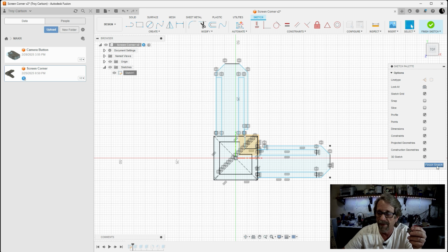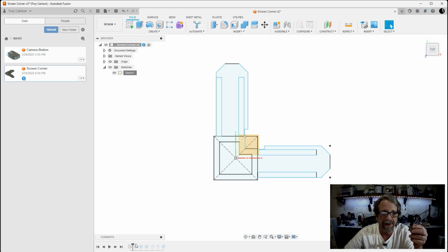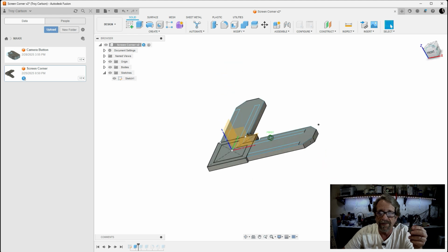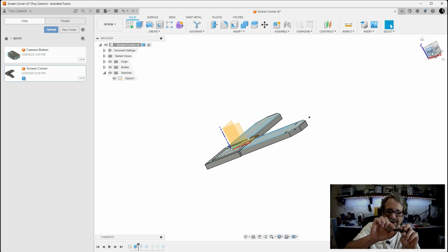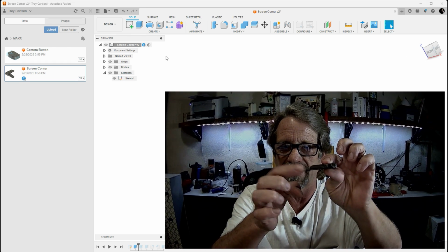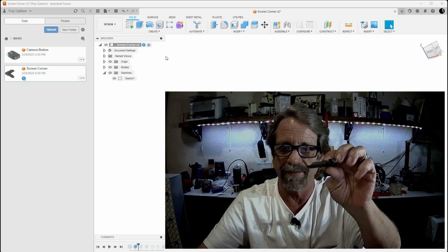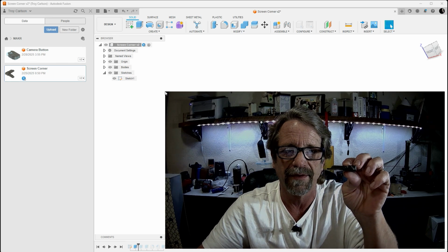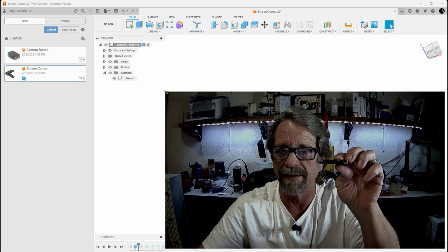But from here, then we go ahead and finish the sketch. Next thing we did was draw up just the thickness. Make me a little bigger here so you can see it. But this little tab that's sticking off right there, we pressed and pulled the whole thing up to that thickness to start off with, since it's the whole item.